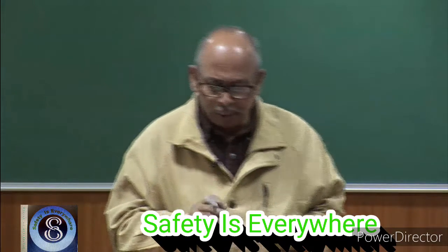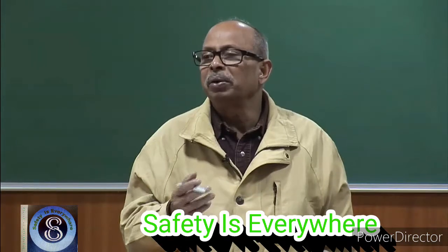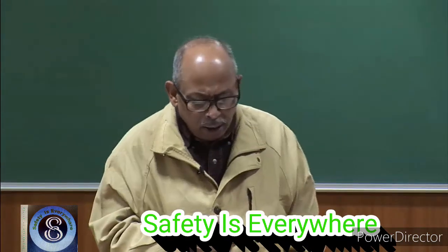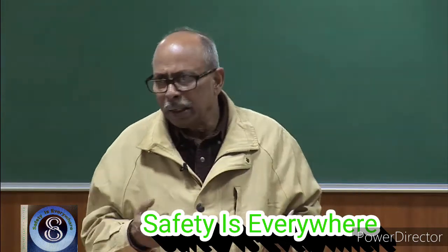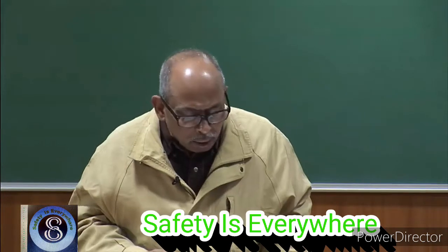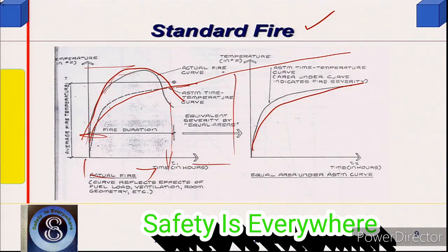Some measurements were also done somewhere. Similarly, in case of fire, the standard fire was arrived at by a kind of consensus of experts, ASTM standard fire or Indian standard fire, which is basically adopted from the appropriate international code, and that fire is something like this, the ASTM time-temperature curve. So, what they do is this monotonically increases, it does not stop. As the time passes, the temperature is higher than the real fire.